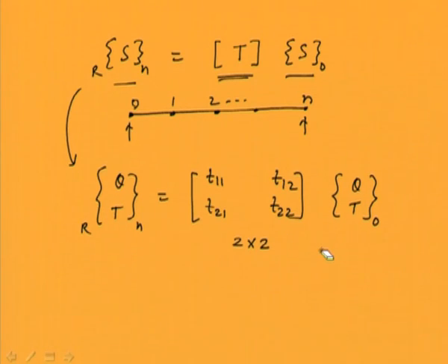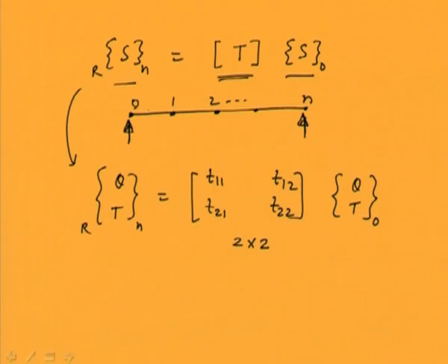Now we need to apply the boundary conditions. So let us say for this particular case we have simply supported ends. Now to solve this particular equation, we need to apply the boundary condition, and in this particular case, we have supported this rotor over frictionless bearings. So they are not providing any torque. That means the ends of the discs are free. So here we have free end conditions.